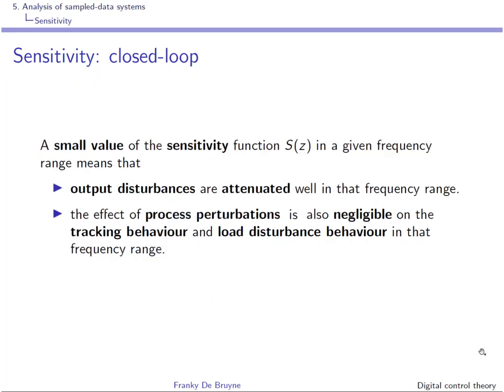A small value of the sensitivity function in a given frequency range, and typically it will be in the low frequencies, omega 0 to some omega 0, means that the effect of process perturbation is negligible in tracking and load disturbance behavior.